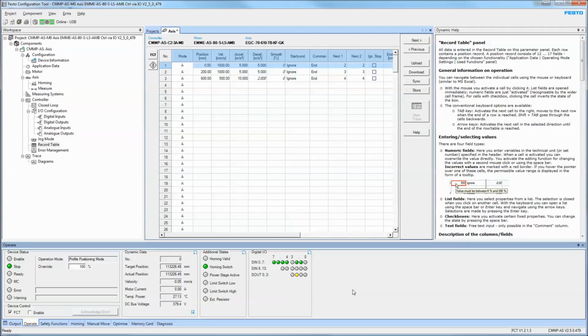The 24 volt signal is going in and out. And the bottom connectors at the front and back need to be hooked up to your motor and your encoder. Without that, you can't do anything. As well, the front of the controller has an X40 connector that is for safe torque off signals. For example, hooking up an e-stop, those need to be wired. Otherwise, you cannot enable the controller.